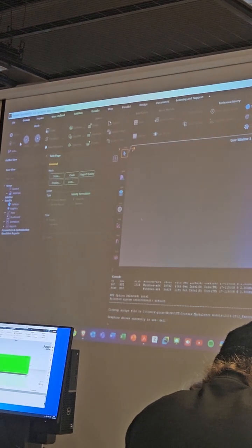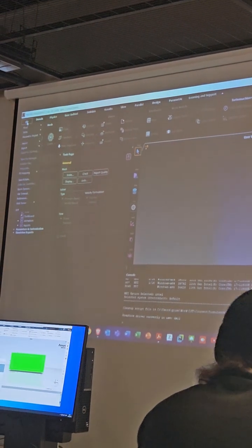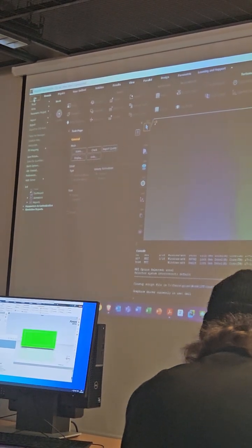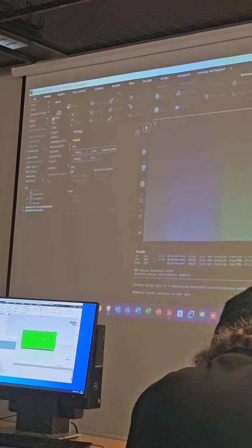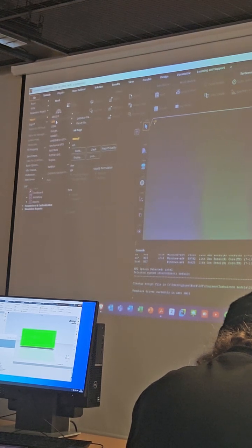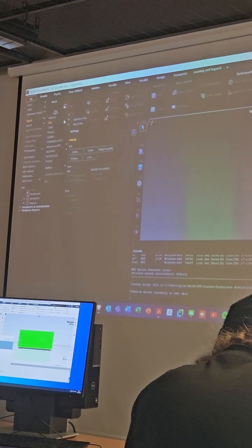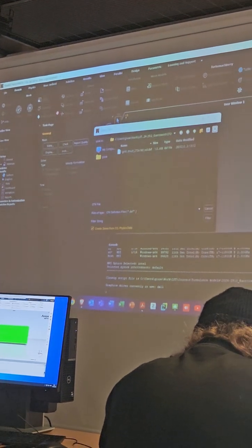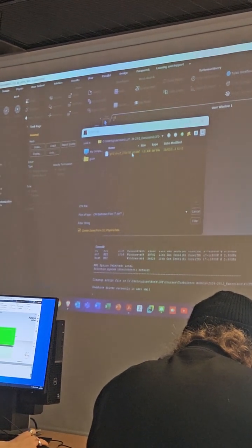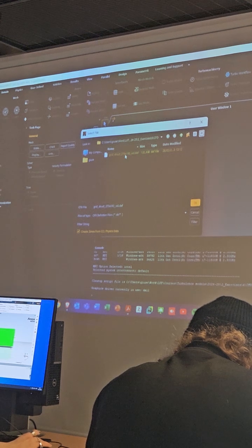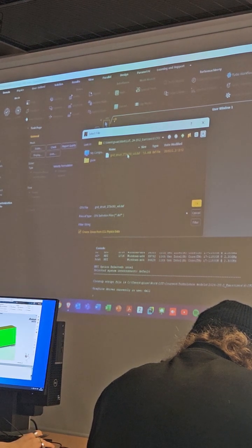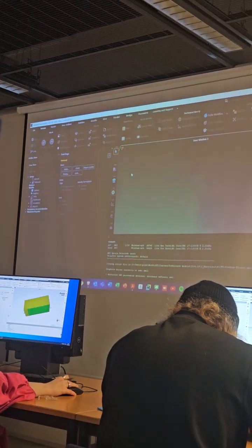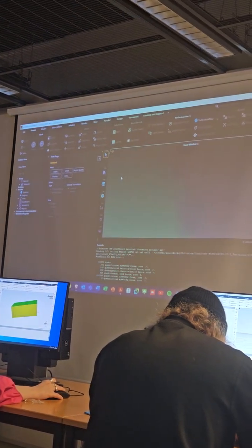So as a first thing, I upload the def file, that is the geometry and the mesh file. So from File, Import, this is a CFX generated file. So I need to select this CFX definition file. And there I can select the def file that I want, the one that you can find in Moodle, and read it.